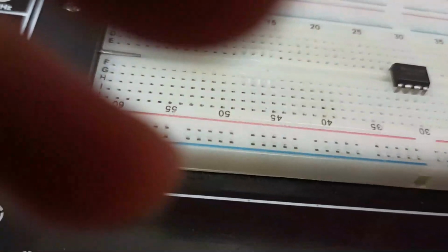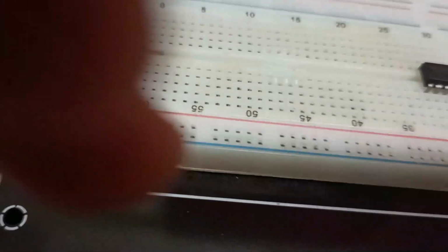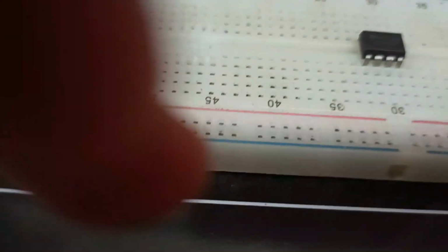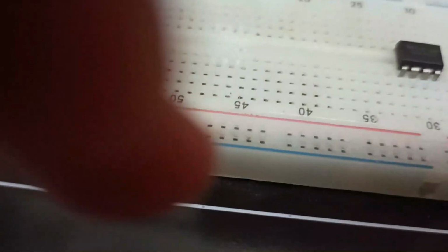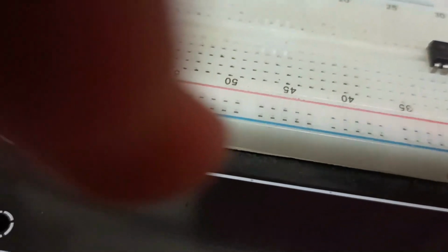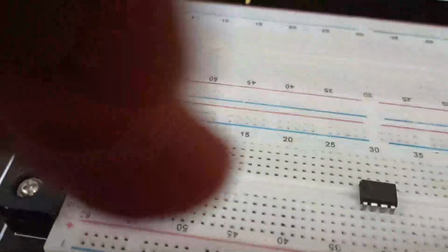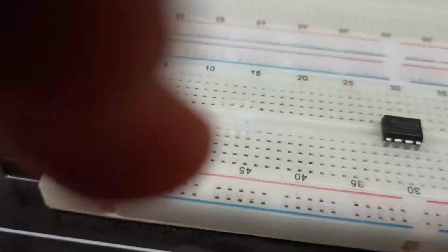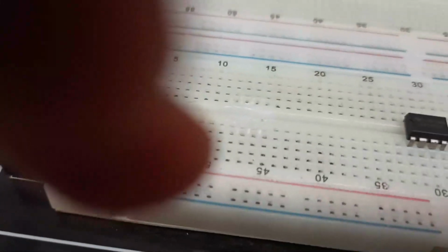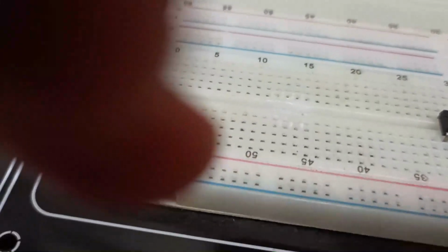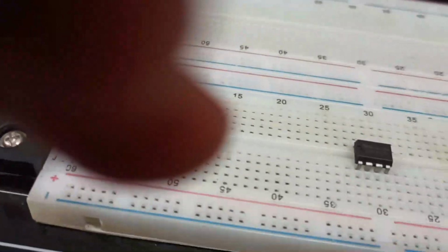So what my next task is, see, some of the precautions that you have to take while operating with op amps is, remember, there is always a dual power supply needed for op amps. Okay, you ascertain that you exactly are getting plus 15 and minus 15. Not that in one direction you will be getting plus 15 volts, in the other direction minus 13, like that. It is not advisable. In this case, the IC will burn.